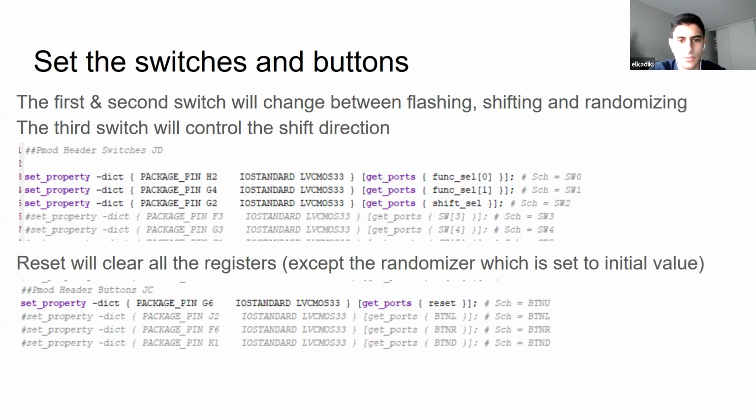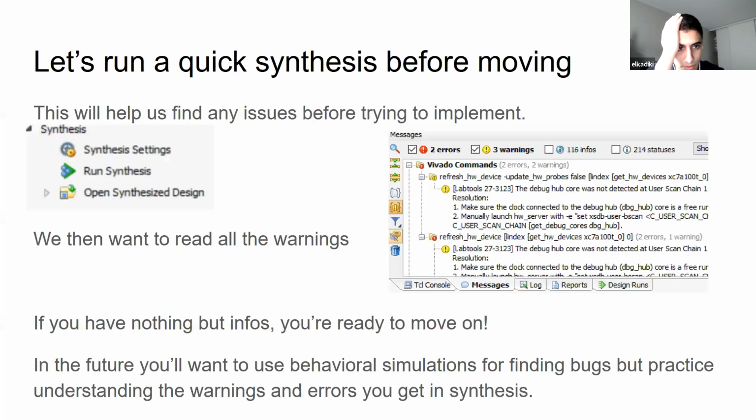All right. That's 4 lines, guys. I think we can move on. Now we can run the synthesis to see if we got any errors. You shouldn't get any errors at all, or any warnings or critical warnings. If you do, let us know.